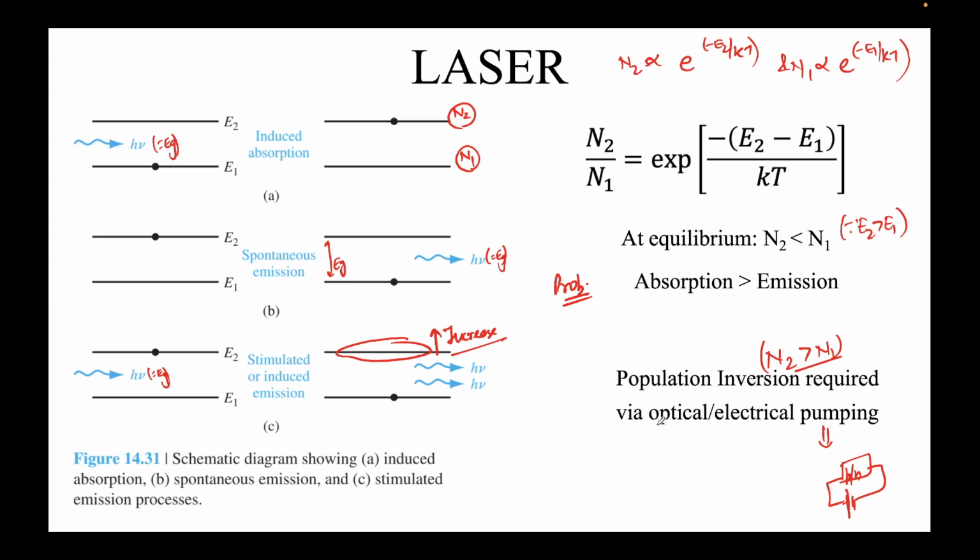Or you can do it by optical pumping. So optical pumping means you shine light, you shine so much light. We solve these kinds of problems when we shine light, and we see your minority carrier diffusion equation comes to the picture, just try to recall that. We did a couple of problems where we are shining light on a long piece of silicon, right? And we're shining light only on the edge of the silicon, and how does the minority carrier charge profile look over time, right? We solved it over length also in steady state. So we solved those kinds of problems before.